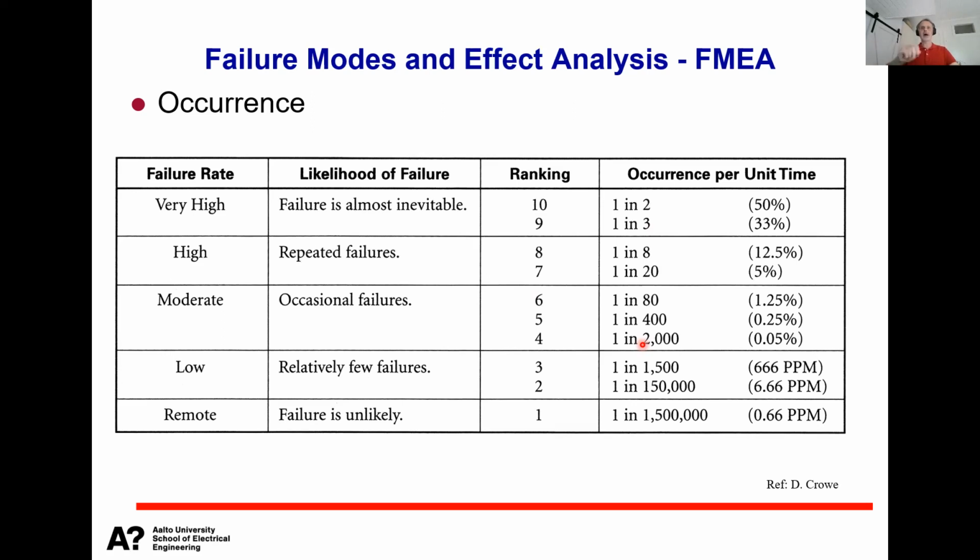In the repair center, they are not doing very detailed analysis of the actual failure mechanism, but they are at least marking the failure mode. So, this product during the warranty time was brought back because the battery had died too early, and they changed the battery. So you will get actual data on how many battery returns you had during the warranty period of, say, two years. And then you have really a quantitative FMEA.